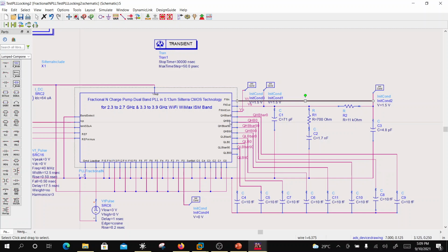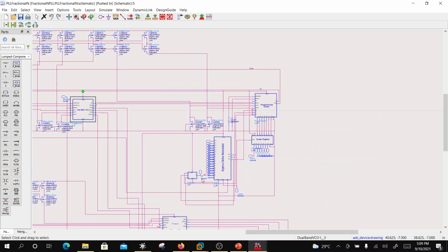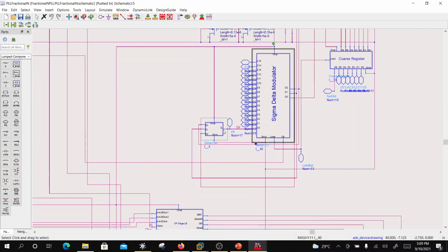Okay, and over here you see C0 to C5. That's your coarse input, and then there is a fractional N input. One more thing I wanted to show you is that in this case a sigma delta, with a lower bit, of course again establishes some kind of a spur in the output. So remember, for n plus 1 we were getting a spur, so we went from n minus 3 to n plus 4, 8 states.